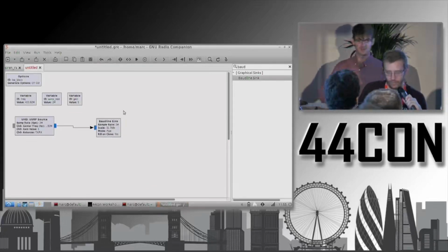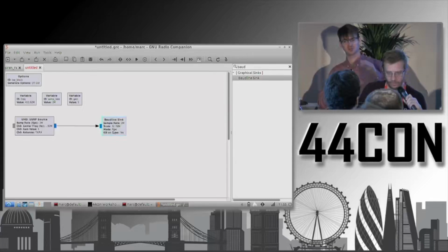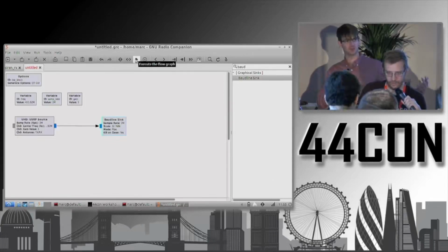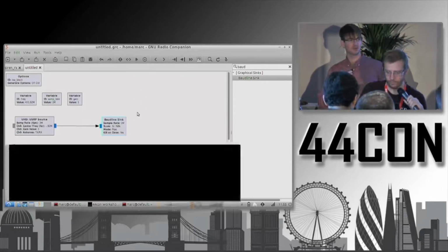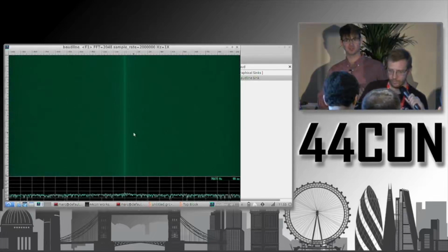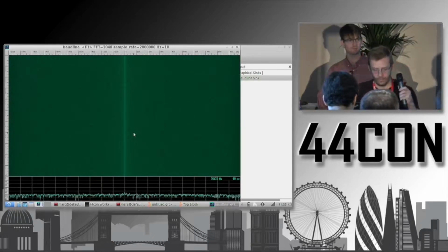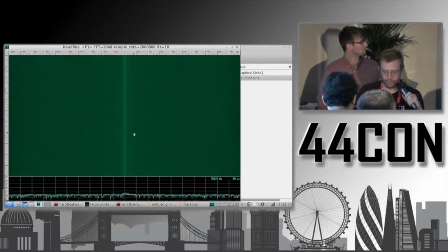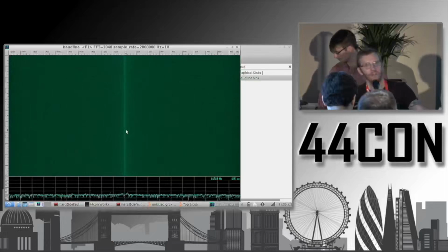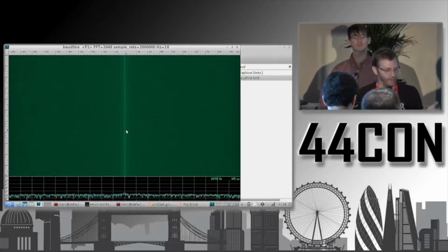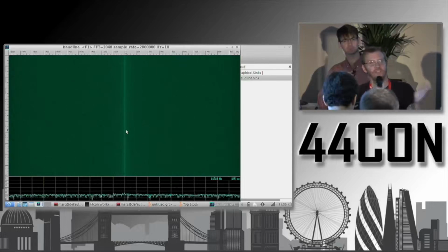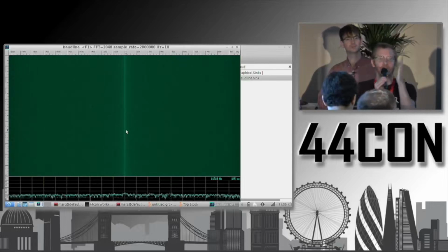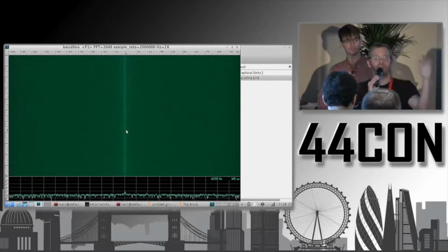Just to clarify what's happening there, the signal over the air is overloading the receiver, which is causing all those images to show up, the aliases. So if you see that sort of distortion, know that sometimes it's the front end, and you should try backing the gain off rather than trusting that that's what the signal actually looks like. It's common, especially on lower quality radios like these RTL SDRs. They just don't have very high quality radio components, so you'll often see this aliasing where you have one signal in the center and then multiple copies going out.